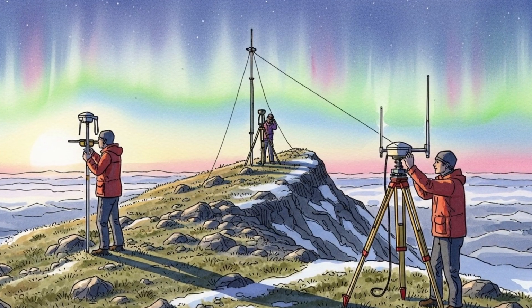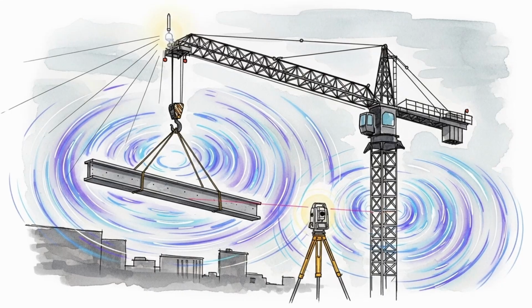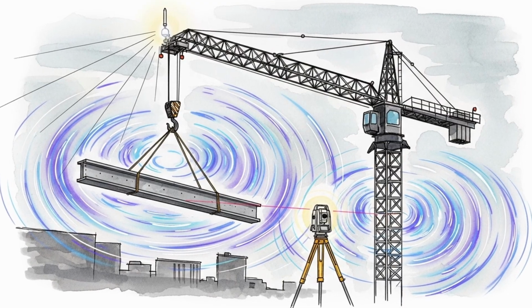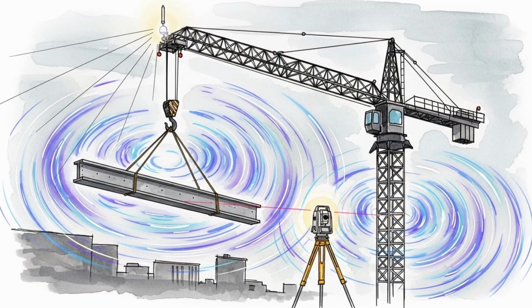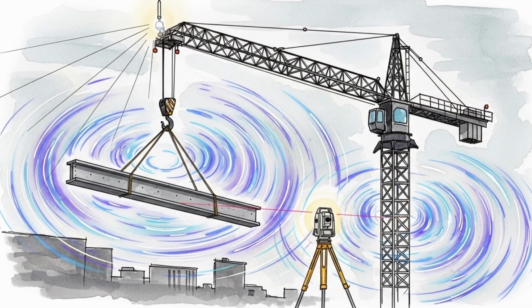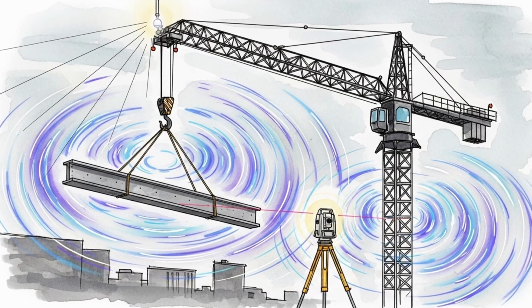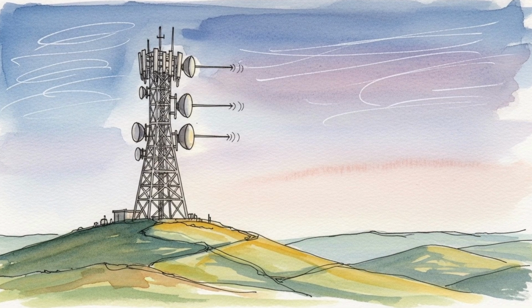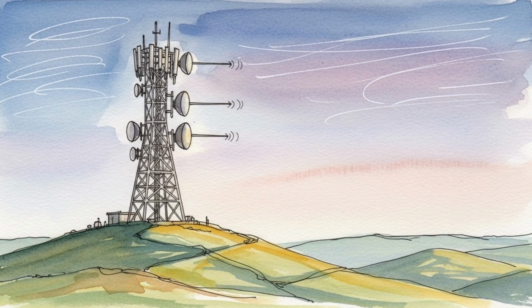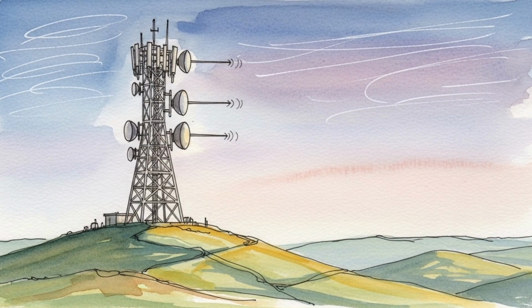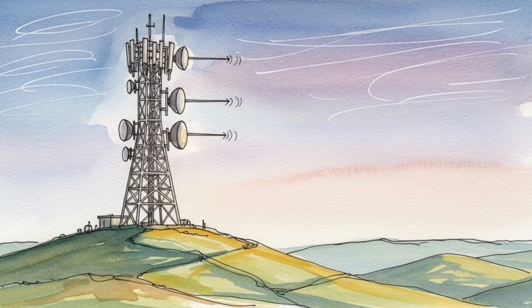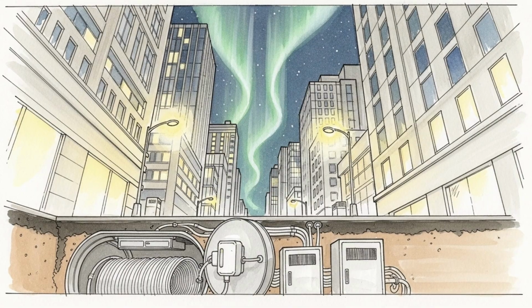Transmission lines collect induced voltage in proportion to length and orientation. Very long corridors accumulate higher end-to-end voltages. Lines aligned with the regional electric field see stronger effects than perpendicular lines. Grounding practices at substations set the return paths. Series capacitors change the effective impedance at low frequencies and can limit some direct components, but they also require controlled bypassing to avoid overvoltage or resonance during switching and faults. These details are handled by procedures before and during storms.